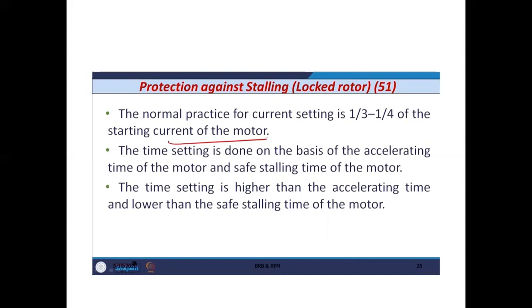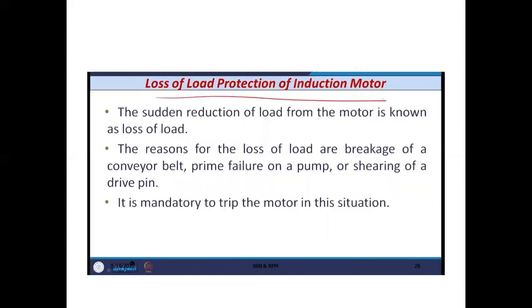The next point is the phenomenon known as loss of load protection of induction motor. The sudden reduction of the load from the motor is known as loss of load. It may be because of the breakage of a conveyor belt, or the prime failure of the pump, or shearing of the drive pin.